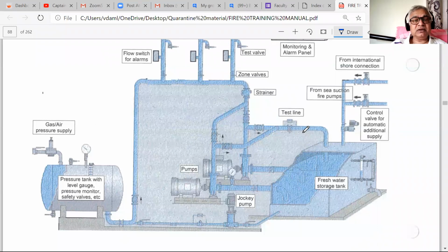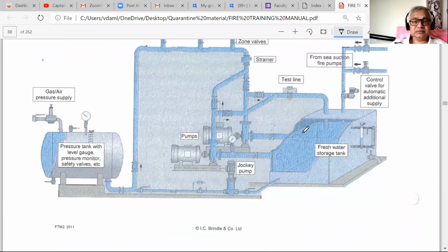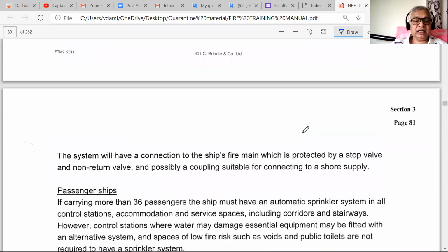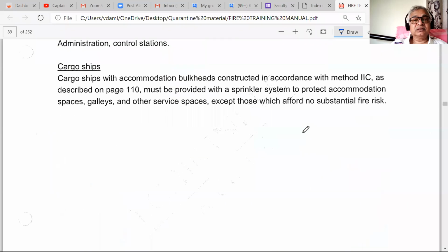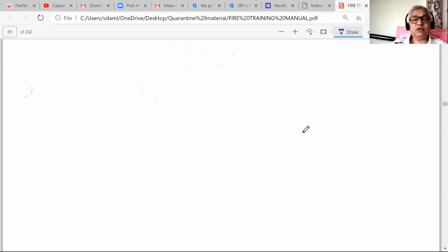Especially when we talk about any one of the fire systems, what we need is to have full understanding of various alarms and switches which are there, especially alarms, because when you get an alarm, you take action. If you don't identify alarm, you can't take action. That is exactly what goes wrong. So you have to know what to expect on every equipment.